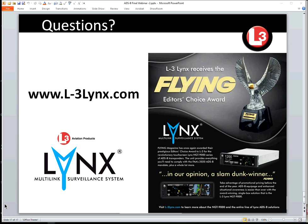The good thing is if that airplane were to travel overseas, be exported to Europe, this device actually meets all the mandates that they would have in Europe for ADS-B, and they might want a diversity antenna, we can turn that on via software and add an antenna, and then the customer did not limit themselves by buying a non-diversity unit. I hope that answers your question. Yeah, I think that definitely covers that.